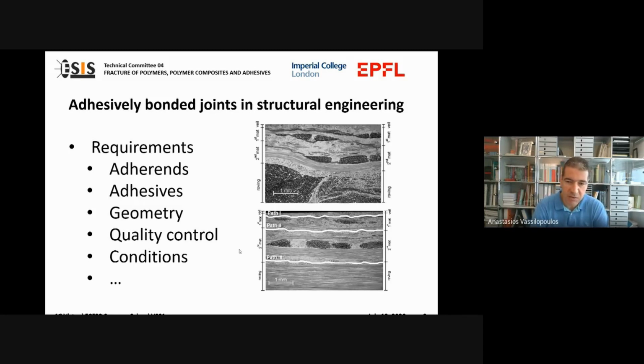And what we should keep in mind here is that if we move in different paths, then we can calculate different energy. It is easier, for example, to move the crack between the unidirectional fibers, and it is more difficult to move the crack in between the woven rovings, because there we have the connection of the fibers to each other, and there are crack stoppers, actually.